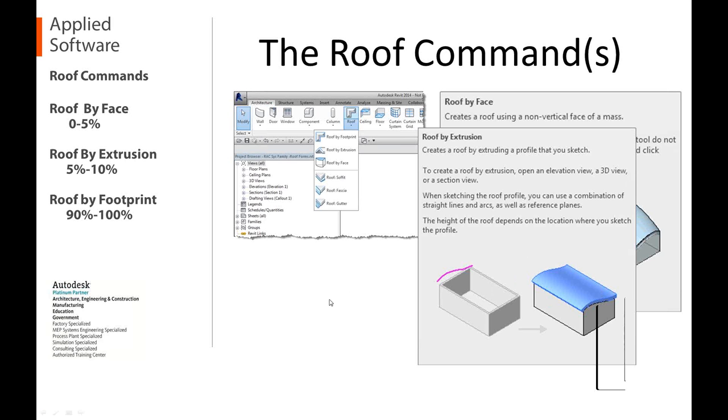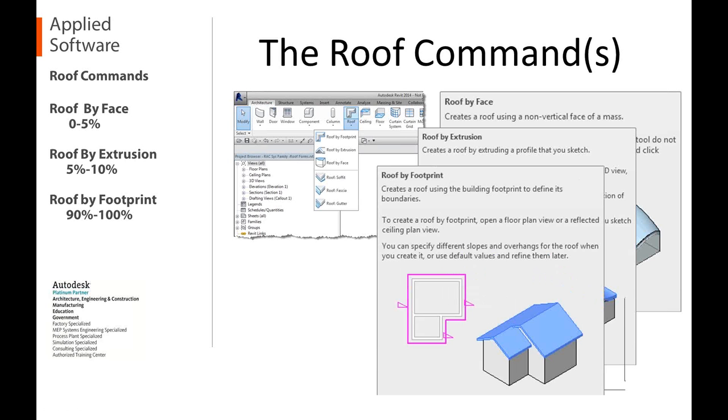And the one that we'll use most often is roof by footprint. What's great about this is that using the roof by footprint, as I'm creating my residential home, I start pushing and pulling and moving walls around. My roof is tied to my walls, and so